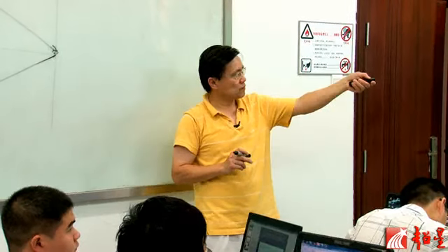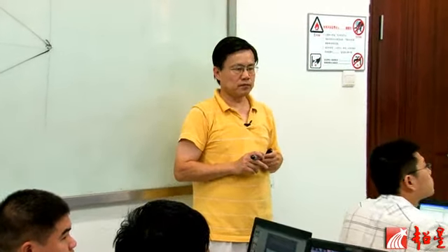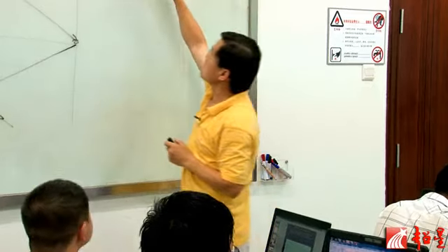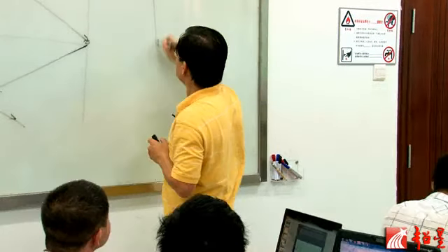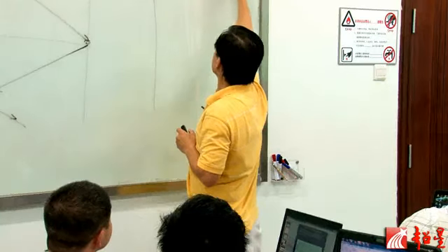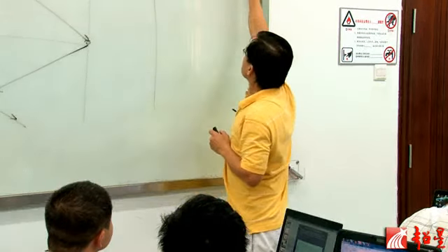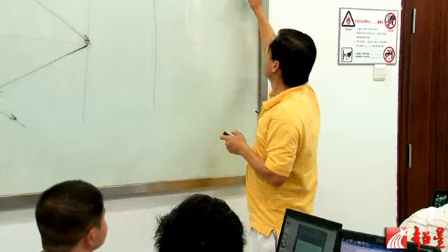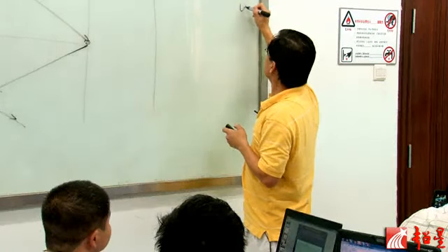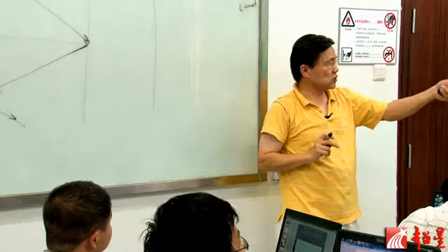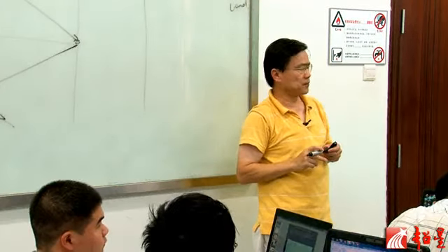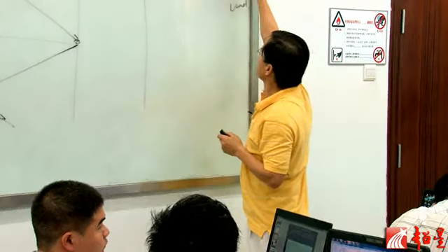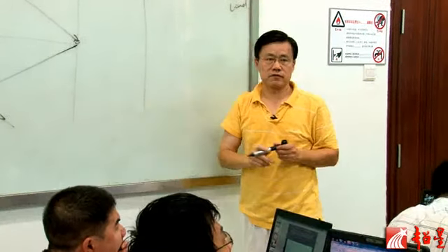That's just this path. But there's another one, which is this one. So I have to deal with that one. The easiest way to deal with that one is just start with the middle and draw 1, 2, 3, 4 nanoseconds. This is the second load. This is the bottom load. What is the reflection coefficient at this point? It's 1/5, right? It's positive 1/5.